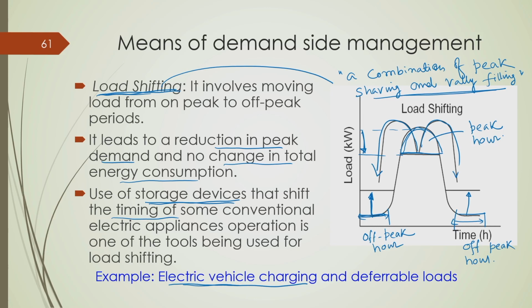How can you make that? You can make some sort of incentive, so that customers will be interested in charging in the off peak hour rather than peak hour. You can make different energy pricing for off peak hour charging and peak hour charging, and thereby you can motivate customers to use their charger during off peak hour, which will give these dual benefits.